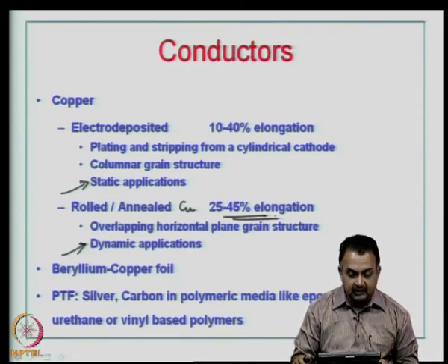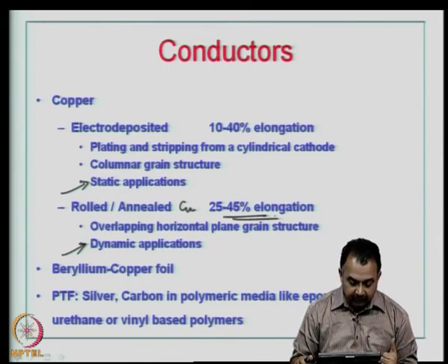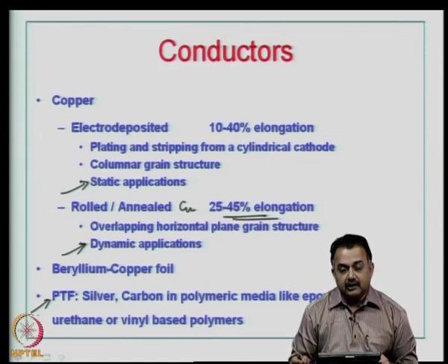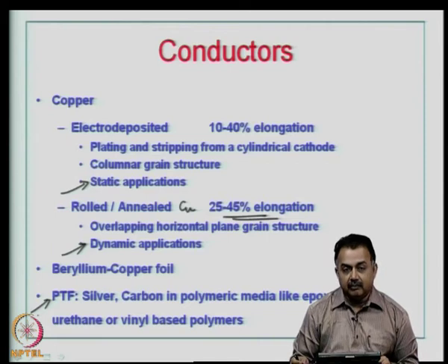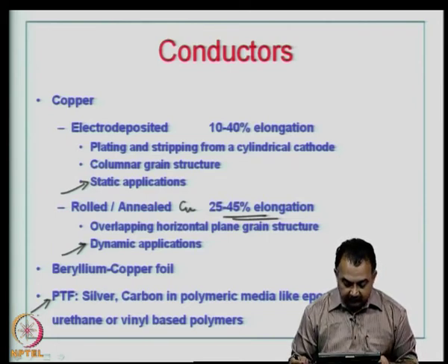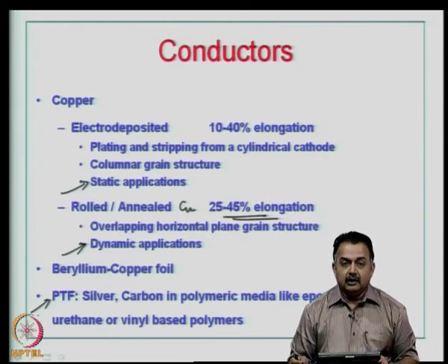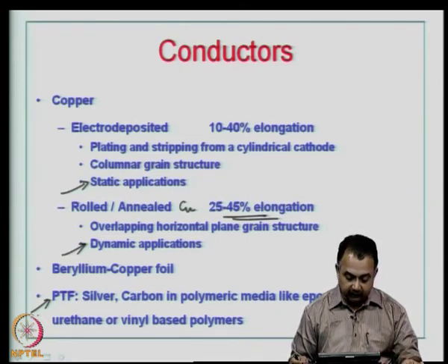or in some cases these conductors are realized by printing, stencil printing or screen printing polymer thick films. So, instead of copper, it can be silver, it can be carbon in polymeric media like epoxy or acrylic, urethane or vinyl based polymers. So, conductors can be realized by electrodeposition foil or rolled annealed copper foils, or by printing using polymer thick films.